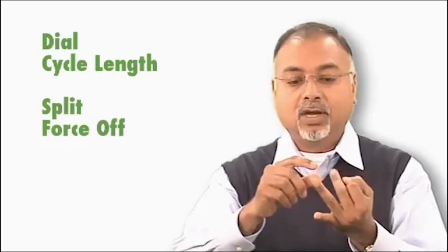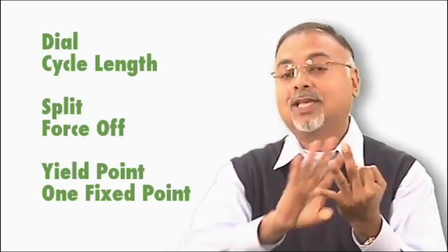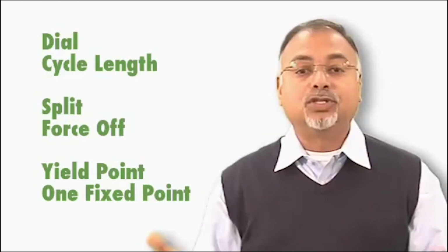Let's look at the modern controllers. They are solid state. Some of them are capable of running 120 timing plans, except if you were to run any more than 5, 6 timing plans, you go into what I call transition hell, which is the signal just goes into chaos when it's switching from one plan to another. The moment you say dial or cycle length, split, force off, or yield point, or one fixed point where offset is a reference, the moment you say these three things, all you're doing is you're emulating an electromechanical controller.